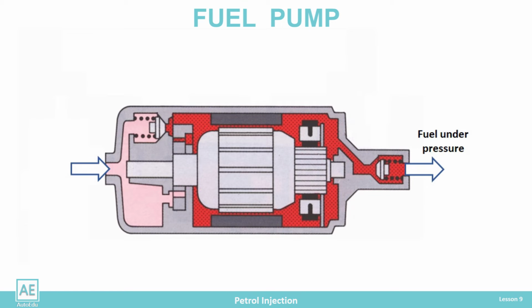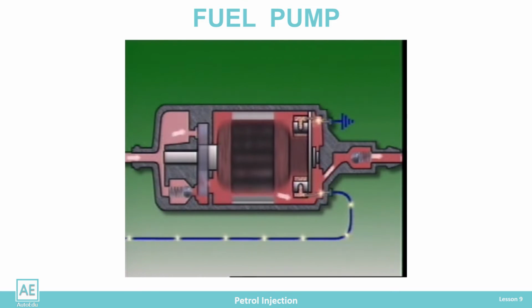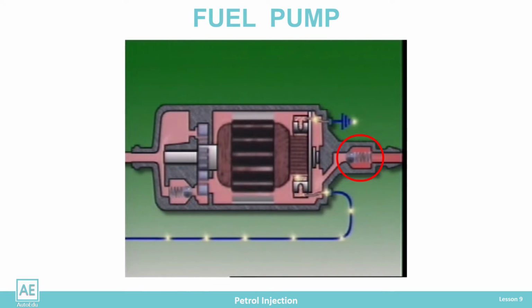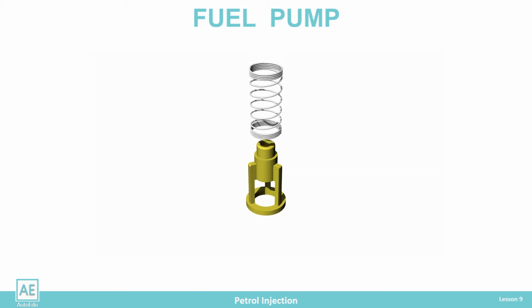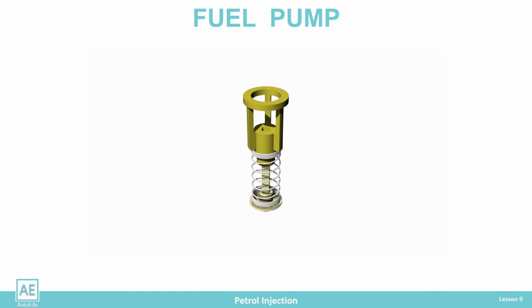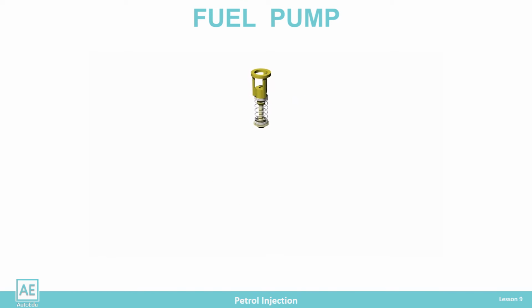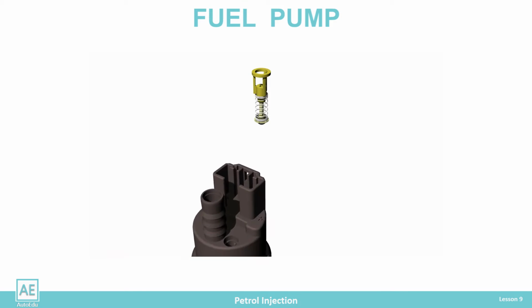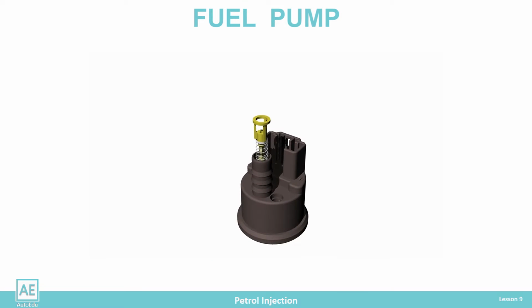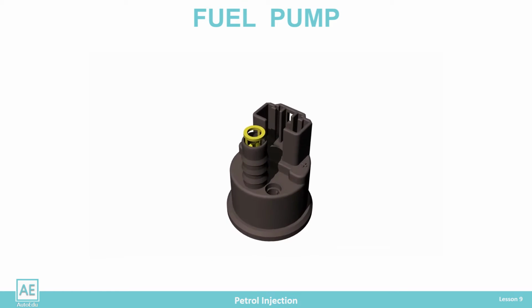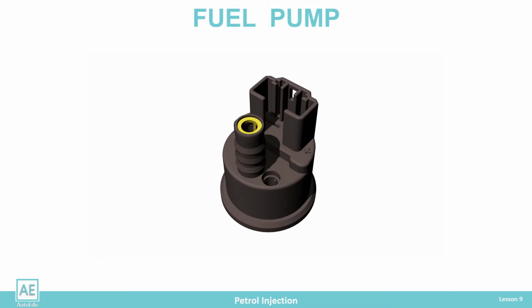The pump pushes the fuel into the system under a certain pressure. At the outlet of the pump, there is a non-return valve that does not allow fuel from the system to return to the tank after stopping the pump and turning off the engine. The injection system requires that there is fuel ready at idle to inject when the engine is restarted. It is the resting systemic pressure. If the fuel is returned to the tank after switching off, it is difficult to start the engine, especially when the engine is warmed up.